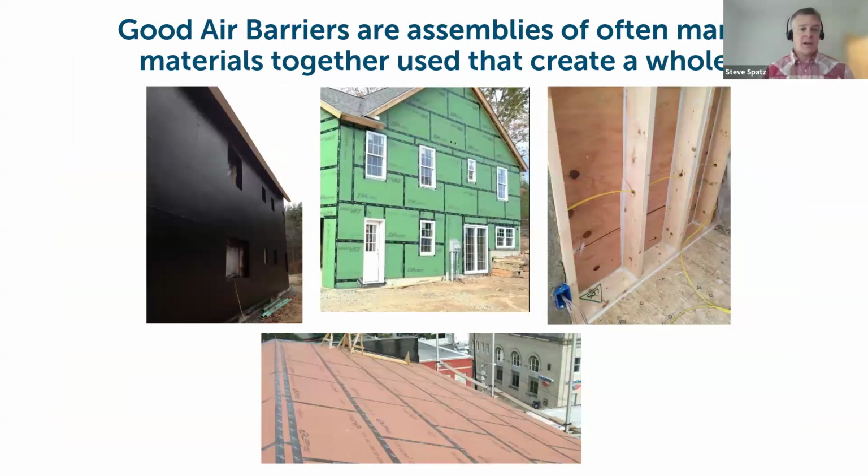And there are a lot of products in the market now that are integrating air tightness into other aspects of the building shell and control layers. So we have fluid applied WRBs that can be put on the exterior of the sheathing layer. That also, because of the nature of how it's applied, creates an airtight assembly of that sheathing layer behind it. Taped sheathing joints of the zip system, or just taping your sheathing joints in general, unifies the assembly. Peel and stick WRBs that are fully adhered are highly effective, providing a WRB and air tightness at the same time and in the same layer.